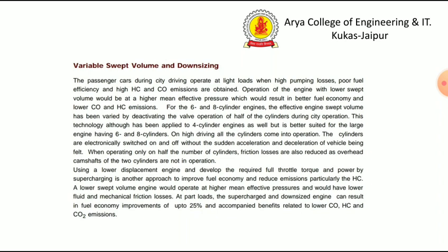At part loads, the supercharged and downsized engine can result in fuel economy improvements of up to 25% and accompanied benefits related to lower CO, HC and CO2 emissions. So these are the basic technologies used for the reduction of SI engine emissions by changing the design parameters.